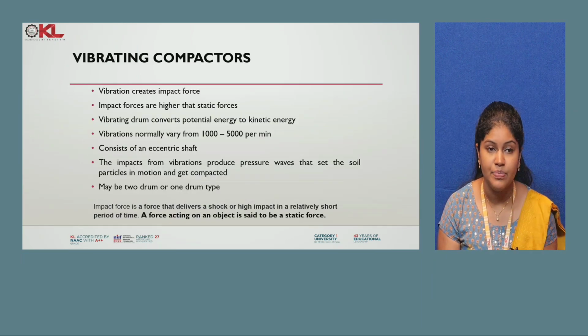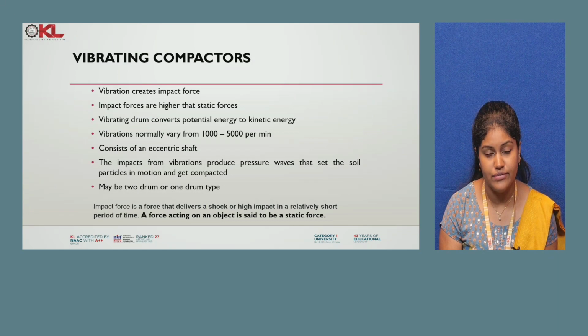Vibrating compactors. Vibration creates impact force. Impact forces are higher than static forces. So vibrating drums convert potential energy to kinetic energy. So here we are compacting by the process of vibration. Vibration normally varies from 1000 to 5000 per minute.